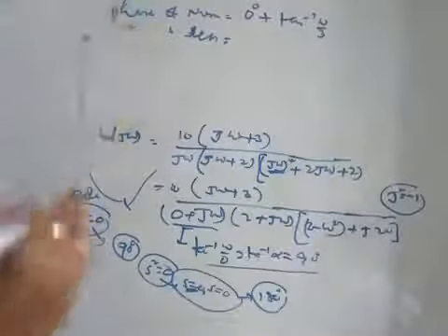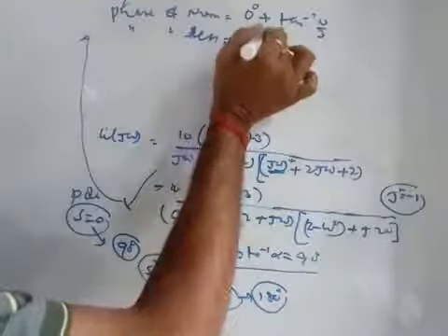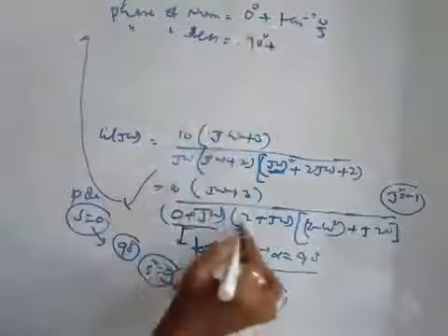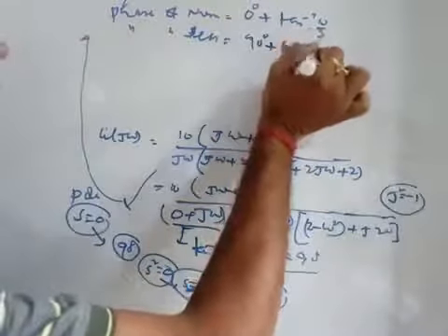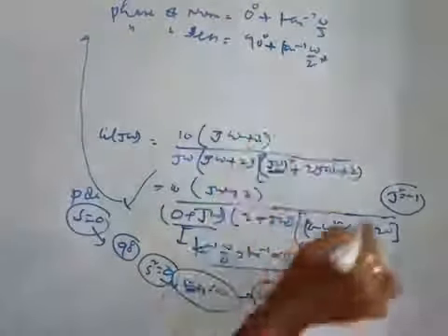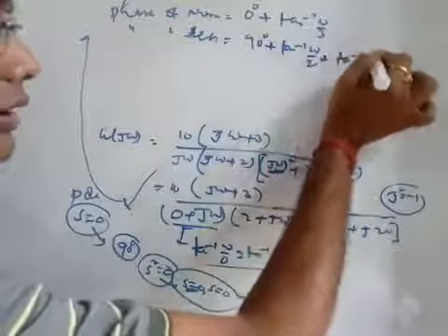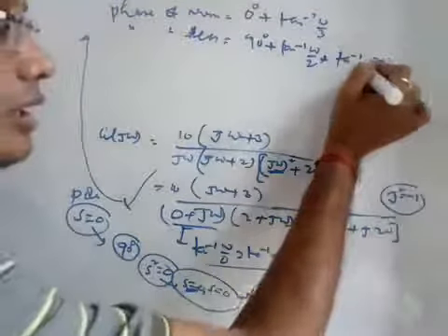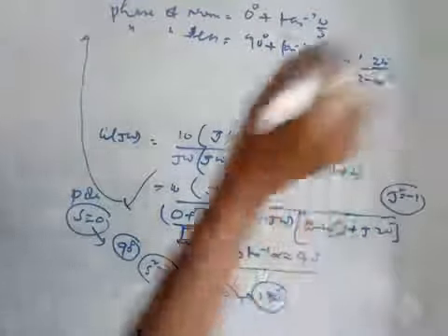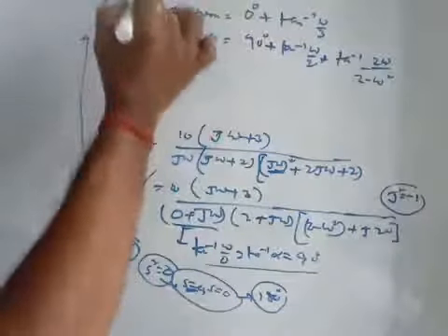So the angle of the denominator, you see here, this is 90 degree plus tan inverse imaginary by real. So this is tan inverse omega by 2 plus tan inverse imaginary by real, that is tan inverse of 2 omega, the imaginary part, divided by 2 minus omega square, right? So this is the phase of the numerator and the phase of the denominator.